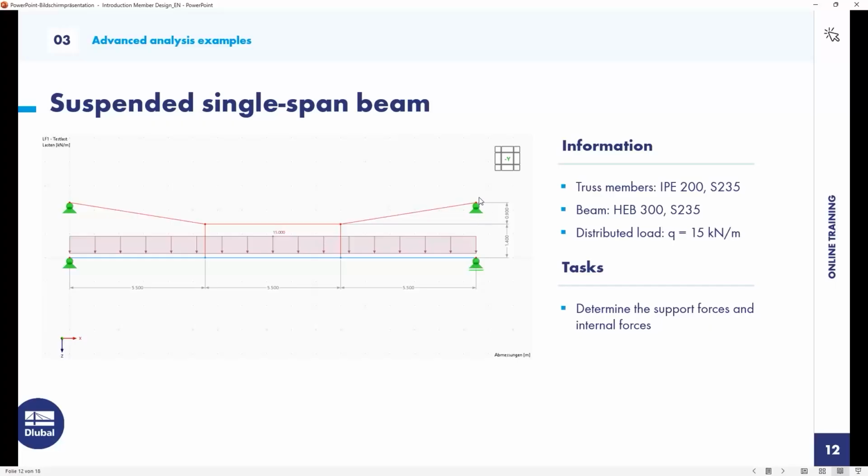That is also necessary because if you imagine that this is like a rope, then you will get very decent tensions on this member. And if we would make the deformation in X axis free, then this rope would simply go to the middle of the structure, and the function of this support would not be there anymore.